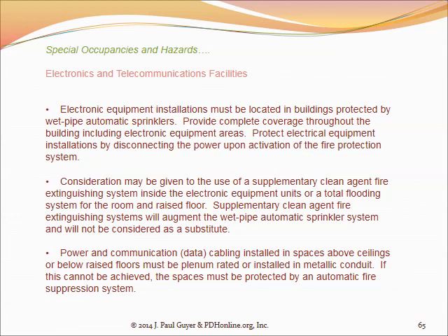That is because of the smoke generation issue. In a typical computer room, the underfloor space and the space above the ceiling are both part of the HVAC system, and the concern is, as it always is, about transferring smoke from where a fire breaks out to other parts of the building through the air conditioning system, the air circulation system.